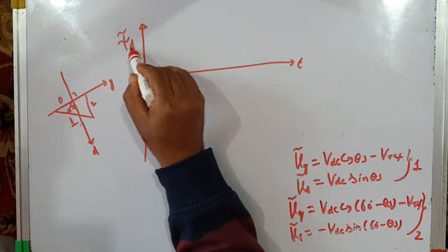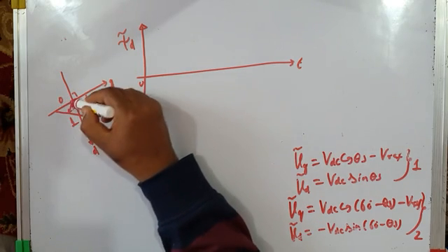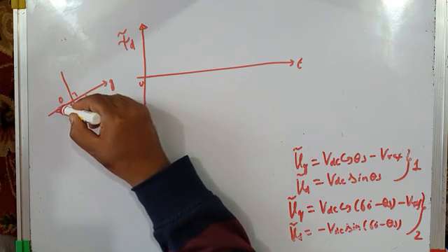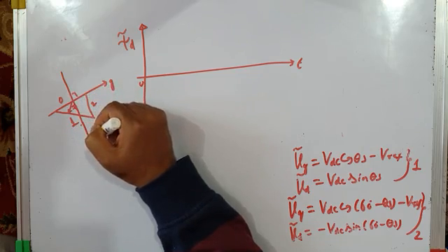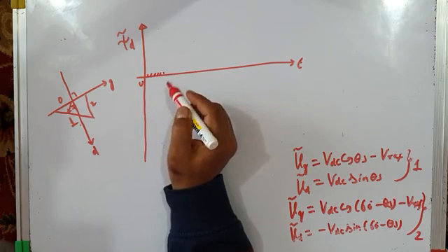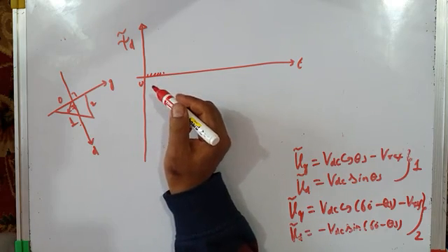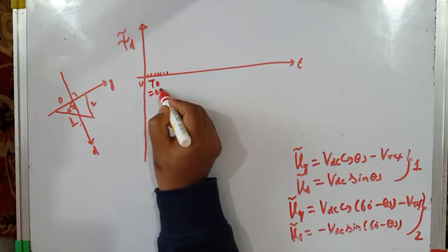Since we are trying to now draw the d axis component of the stator flux ripple vector, when null vector is applied, our stator flux ripple vector moves in this direction along minus q, and it has no component along d axis. Okay, this is for time interval t naught equal to 0.5 tz,